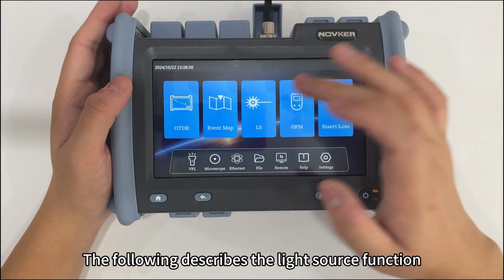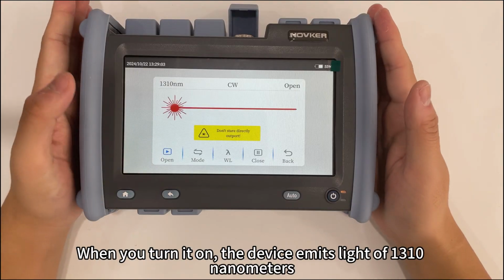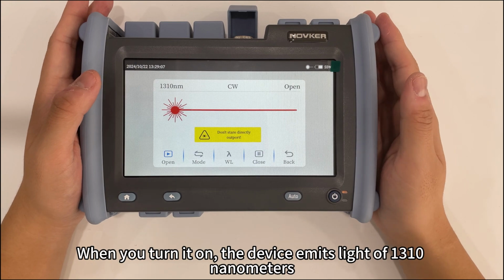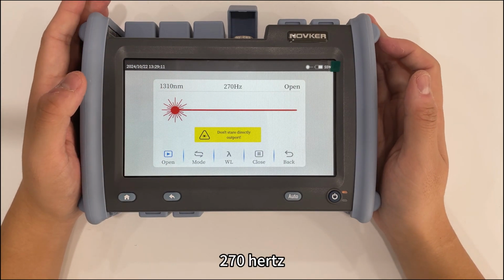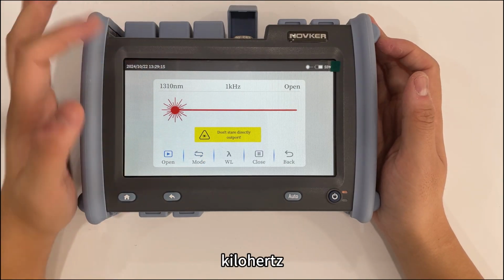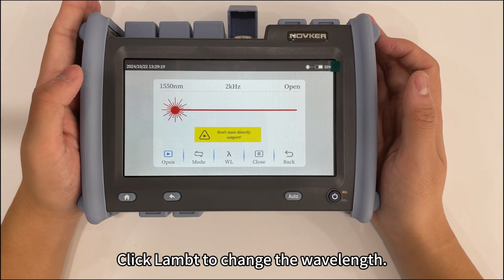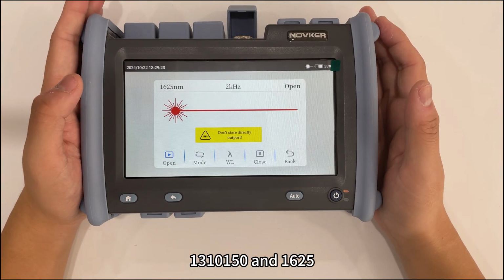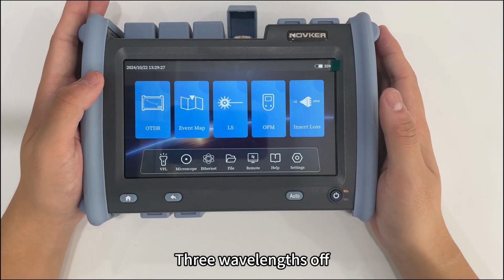The following describes the light source function. Turn on the light source. When you turn it on, the device emits light of 1310 nanometers. Click to change the frequency. 270 Hz, 330 Hz, 1 kHz, 2 kHz. Click to change the wavelengths. This device supports 3 wavelengths: 1310, 1550 and 1625.